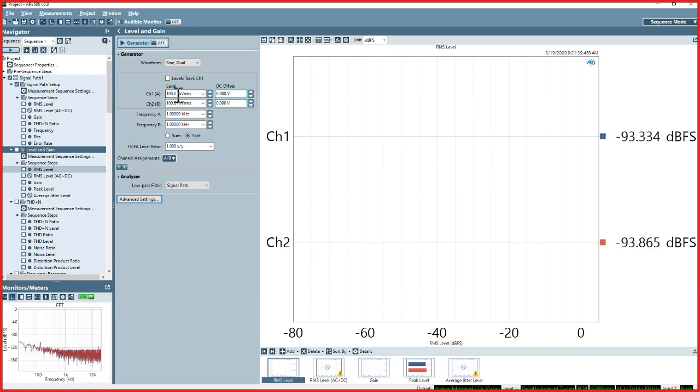If we're talking about testing a chip that has an SACD physical layer interface, and this gets a little complicated, but SACD is pulse density modulation. That is the physical signal itself. That can be synthesized actually by a PDM module.